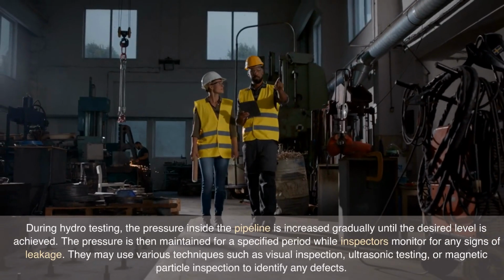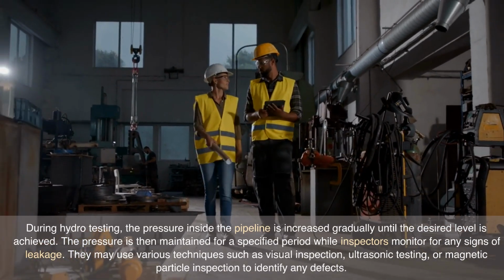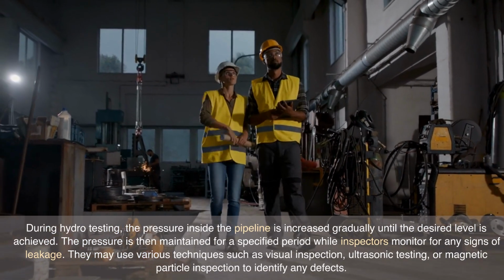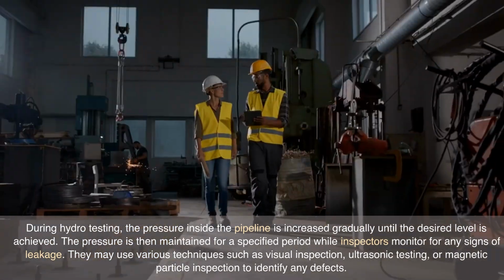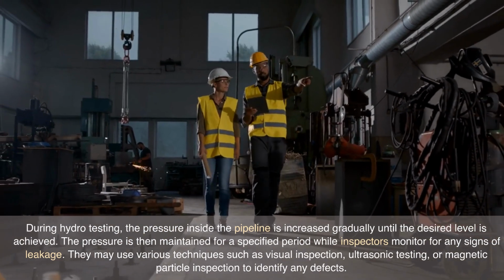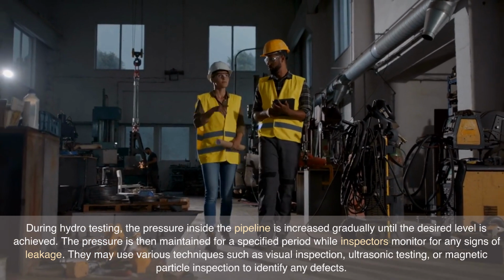During hydro testing, the pressure inside the pipeline is increased gradually until the desired level is achieved. The pressure is then maintained for a specified period while inspectors monitor for any signs of leakage. They may use various techniques such as visual inspection, ultrasonic testing, or magnetic particle inspection to identify any defects.